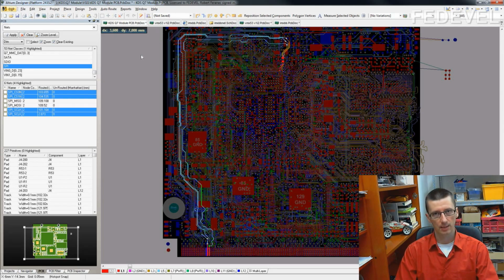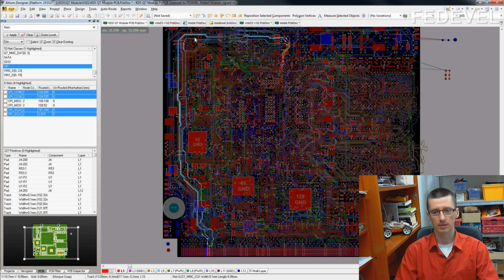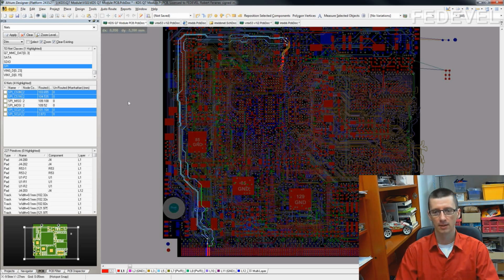because we would like to use same topology for all the signals in the bus, and to do so we need space. At this moment, at this stage of the layout, there is still quite a lot of free space, so that's the reason why it is the right time to do the longest interfaces. When you connect this one, the longest one, locate the second longest one and connect.